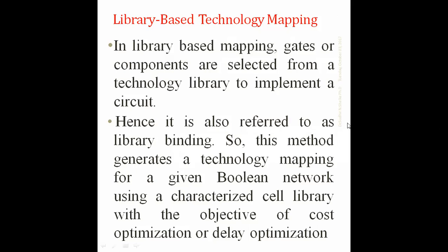Hence it is referred to as library building. This method generates a technology mapping for a given Boolean function network using the characterized cell library, with the objective of cost optimization and delay optimization. The basic aim is to reduce the cost of the design as well as the delay.